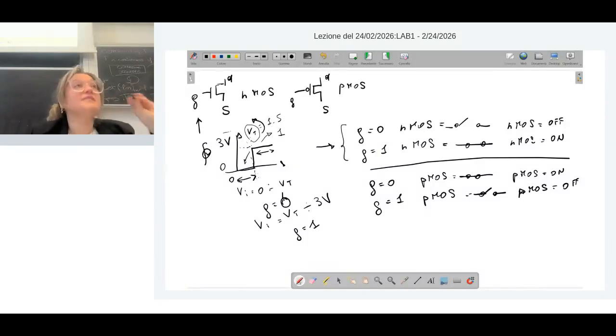It's designed specifically for the transistor. Each kind of transistor has its voltage threshold. Every time that you buy a digital element, an analog element, a circuit component in general, you have a data sheet. In the data sheet, the manufacturer tells you this element has a 1.3 voltage threshold to be on and off. It will also tell you the dimensions and all the other characteristics. Believe me, there are a lot. Okay, so does everyone understand this?